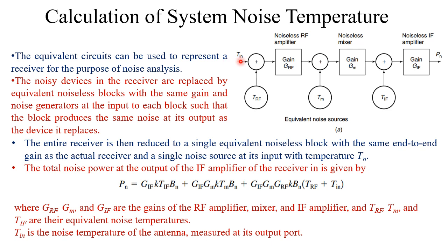And input noise is represented in terms of Tin. Similarly, this mixer stage is replaced by a noiseless mixer along with a noise source Tm.